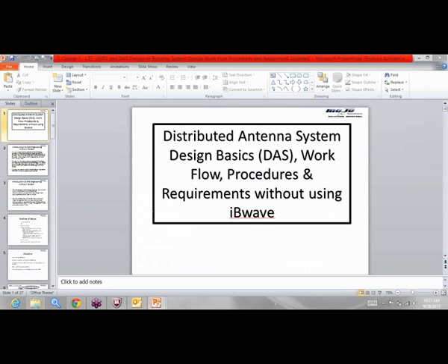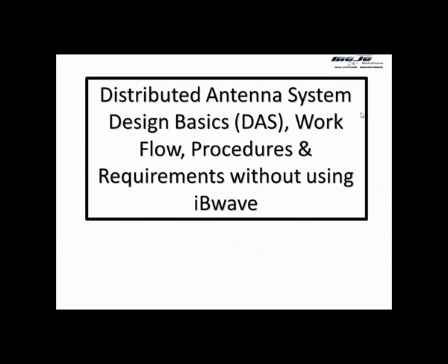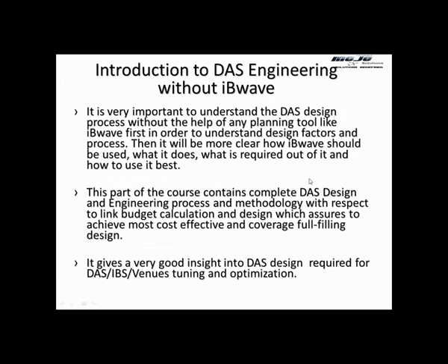So let's start with today's session. What we'll be doing again, we'll be going through the distributed antenna system design, which will include link budget calculation or schematic calculation, the design process flow, and the design requirements and the basic concepts for Ibwave power calculation. Okay, so we will not use Ibwave. We'll not talk about Ibwave, but we'll talk about the terminologies used in Ibwave. So in next session, when we jump to Ibwave, we'll already be familiar with the terminologies and the overall function of DAS.